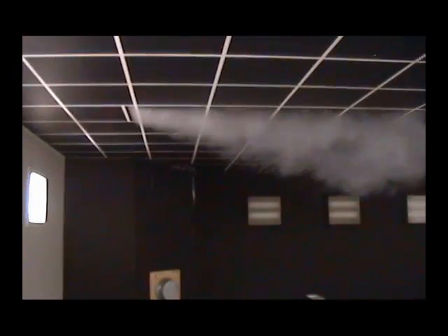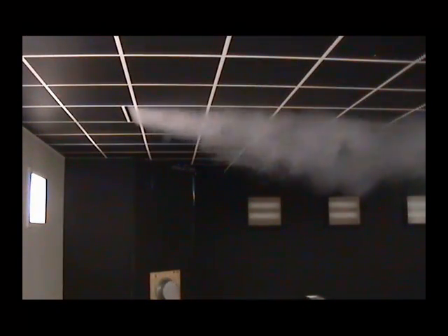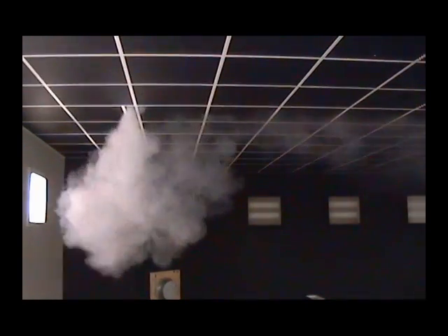This smoke video of the auto changeover diffuser demonstrates the quickness in changing from horizontal cooling discharge to a vertical heating discharge. For the vertical discharge, the heat deflects back to the glass at an angle of about 10 degrees, allowing the mounting of the unit to be in the ceiling from 18 to 24 inches from the glass.